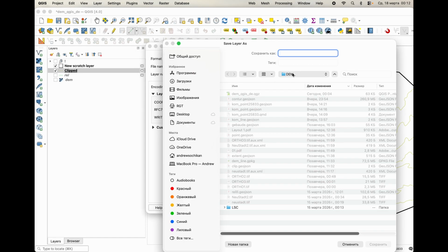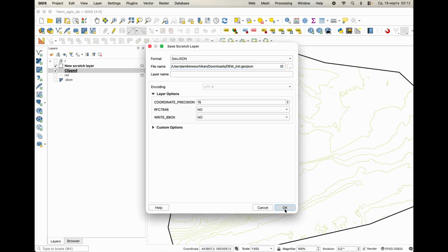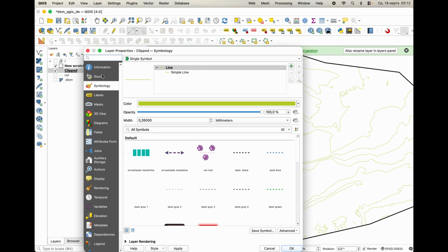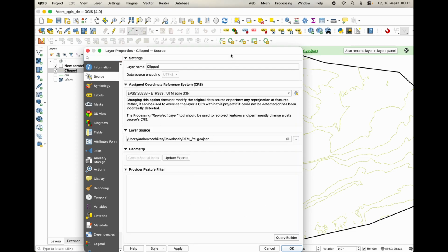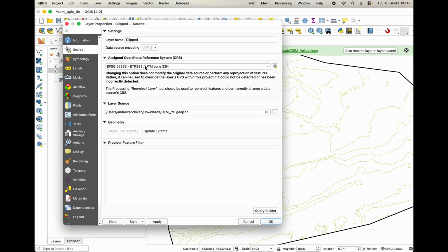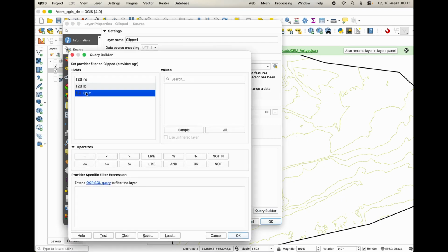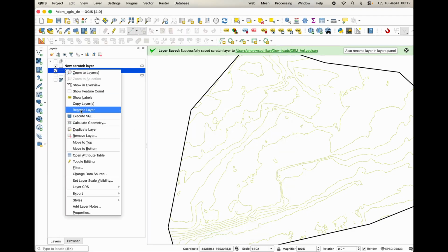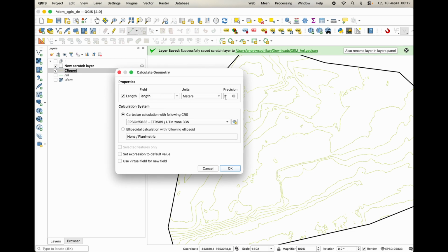A typical issue after contour generation is that the dataset contains a large number of very short contour segments. These are often caused by small terrain irregularities, interpolation effects, or local noise in the data. Technically, they may be correct, but visually, they often do not improve the map. In many cases, they make the result look too busy. And so the next step is to identify these short contour segments and remove them.